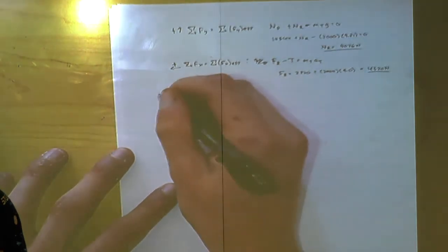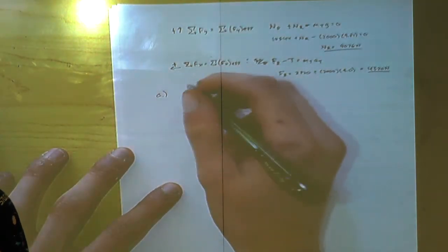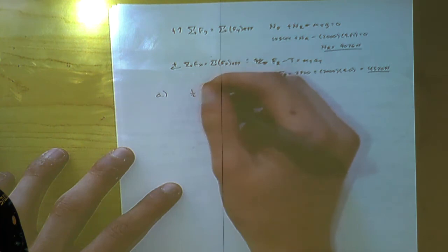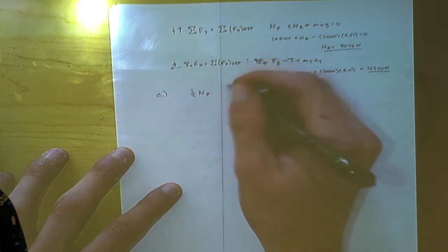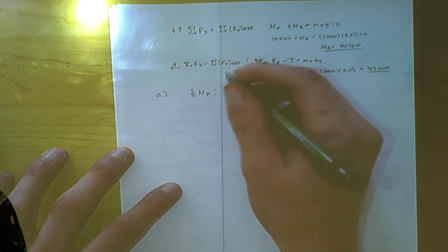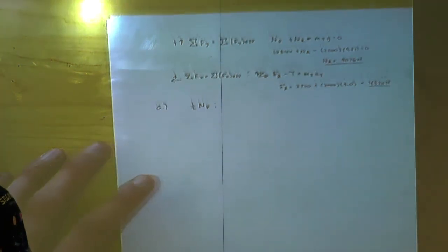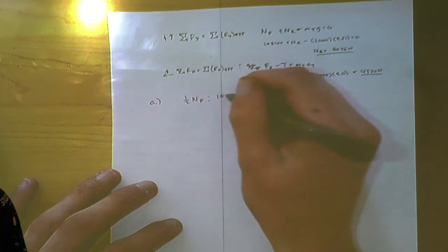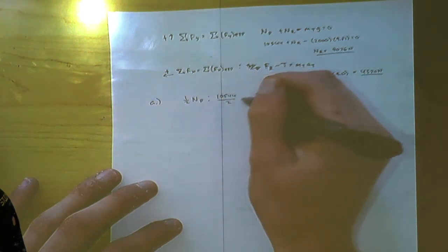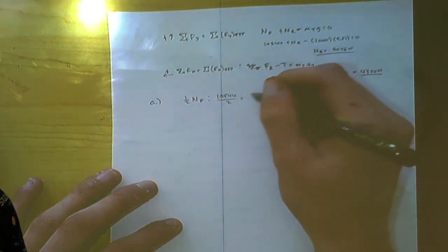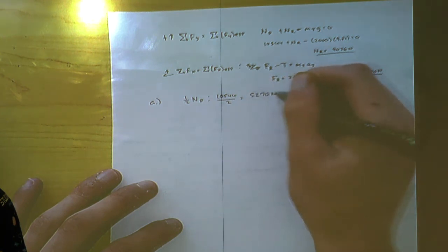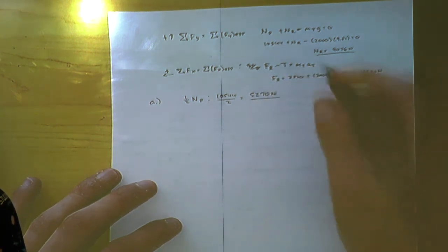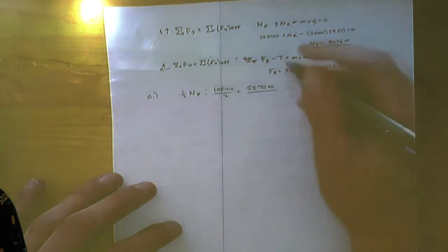So for the reaction at each front wheel, it's going to be 1/2 of the normal force of the front. So we had NF equals 10,544. So that divided by 2 gives us 5,270 newtons for each of the front wheels.